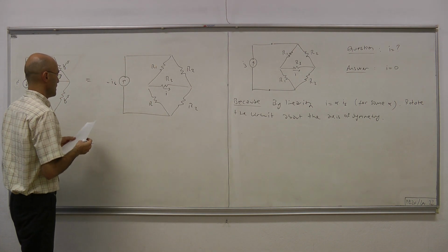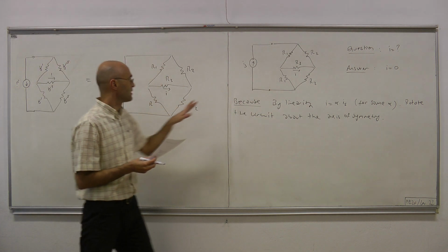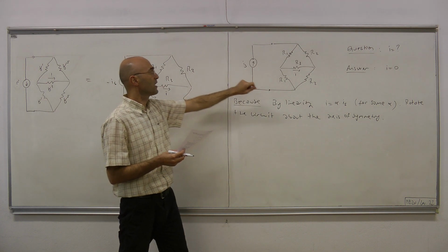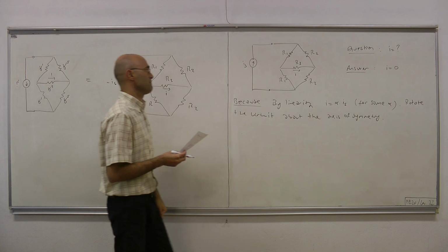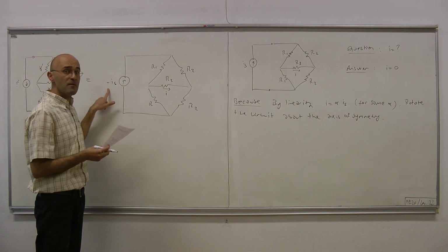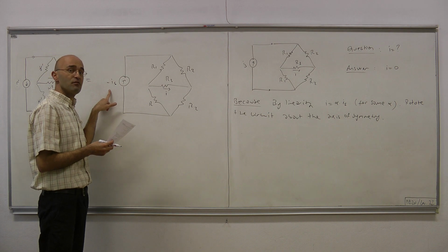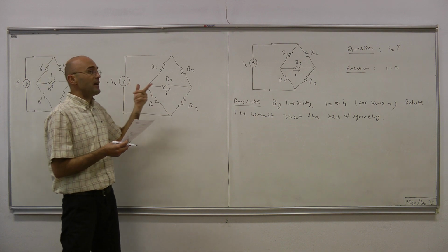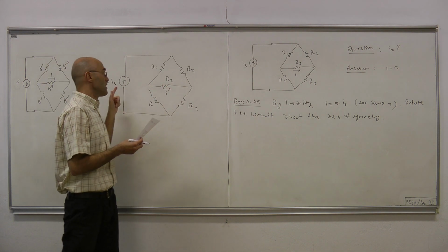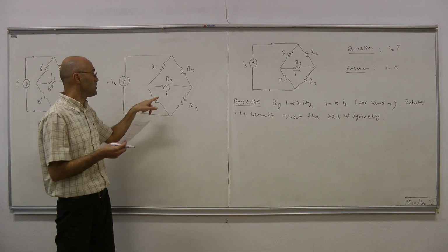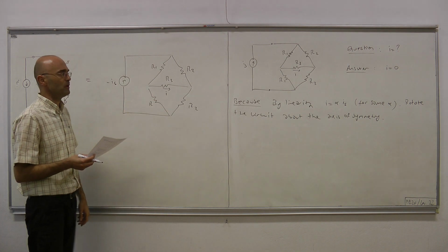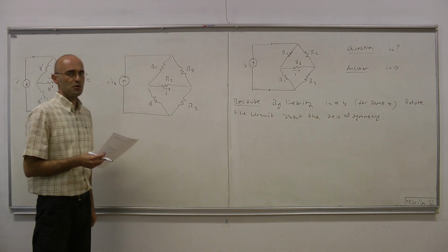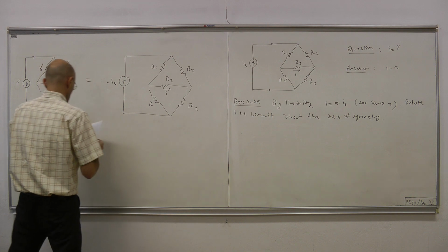And now compare this circuit and this circuit. In this circuit we have IS from the input and that generates some current I. Now for the same circuit we apply the negative of the same input. Minus IS is the input, but it doesn't generate minus I, which it should by linearity, but it generates I. So how is that possible? That's only possible if this alpha equals 0.